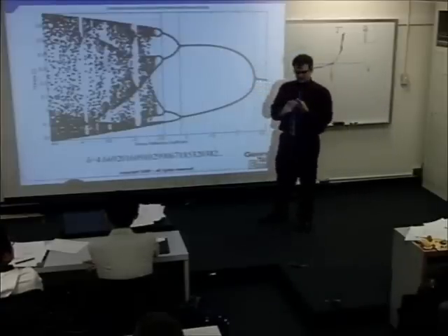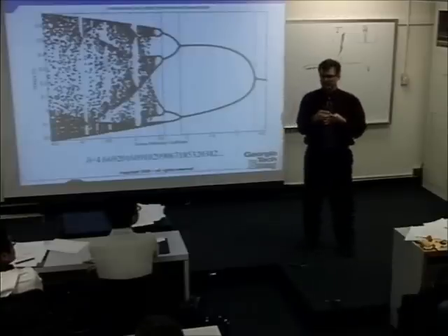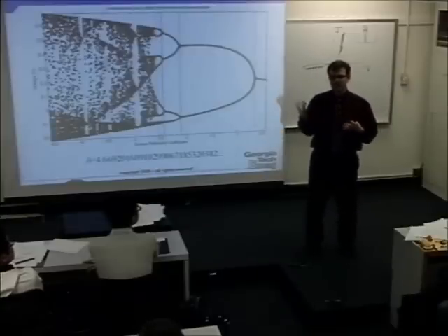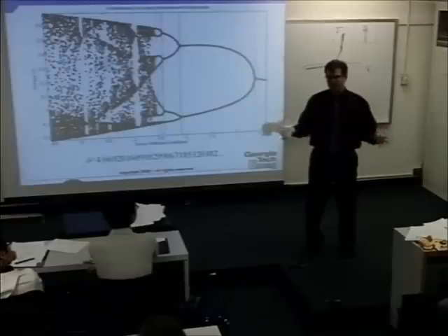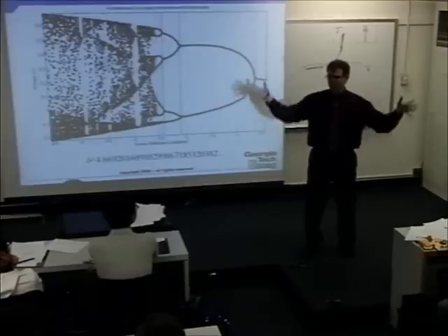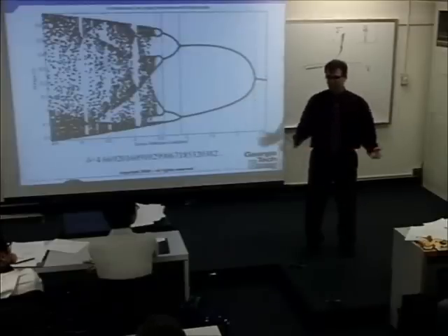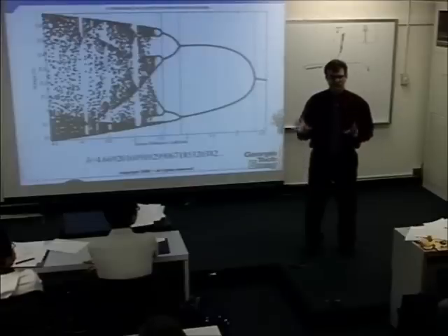You need that. You need a little bit of damping, so you got to put a resistor in there, and you need some sort of nonlinear element, and one that has negative resistance in it, or a source, or something to give energy to the system. Because if you don't have energy, no matter how crazy your circuit is, it's going to decay to a zero state or some trivial state. It needs a little driving the solution.